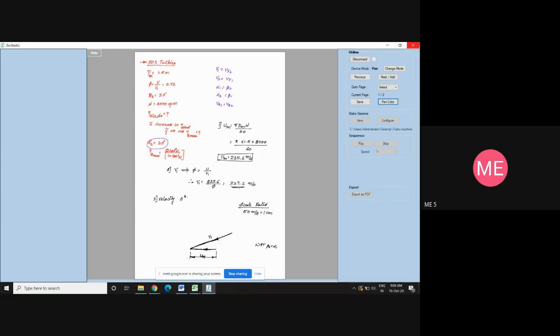Once you've done this, can you tell what is the next step? Simply drop down the vertical line. Write this as VA1. Join this. Complete this figure. So this is VR1. And from here to here it is VU1. So that is all. This is called alpha 1 and this is called beta 1. So from this figure, you find out beta 1 first.